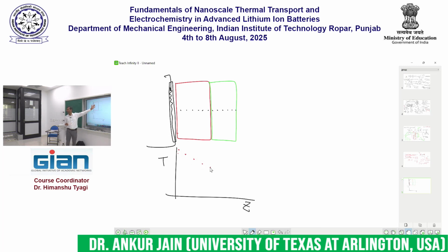What about the green thermocouples? The slope will change. The first thing is that the slope will change. What is the meaning of the slope? What does the slope represent? Thermal conductivity, right? So if these 2 materials have different thermal conductivities, then the slopes of these measured data will be different. So you might see something like this.